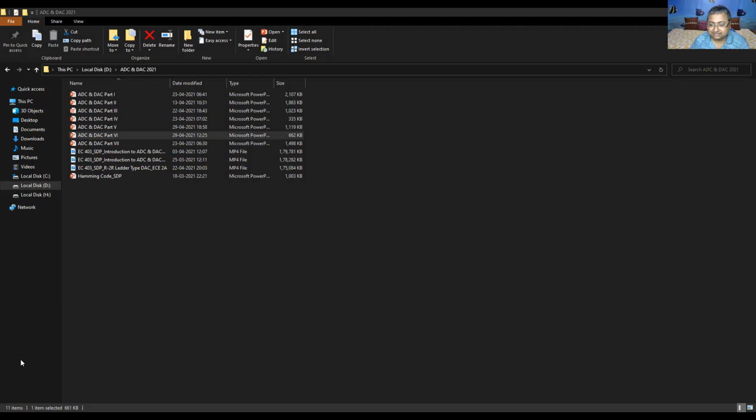So at the time of T2, the V1 is 0, V1(T2). So we can put here and we will get this equation. Similarly for this equation. So N is equal to, here, T2 minus T1. What is the value of this? Now N into Tc. N is the number of clock cycles, and this is the clock period. So this is the total time. So at that time, we will write T2 minus T1 is equal to N Tc. So N is equal to like this.